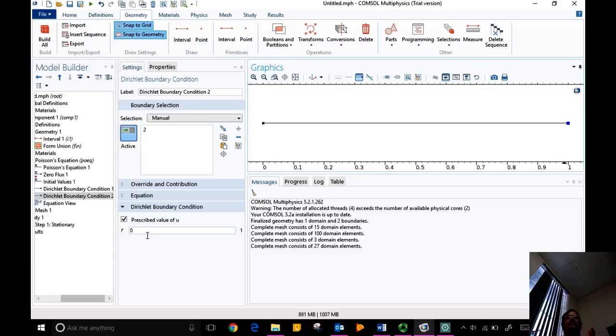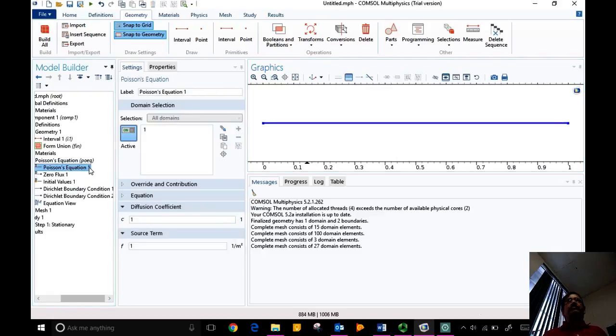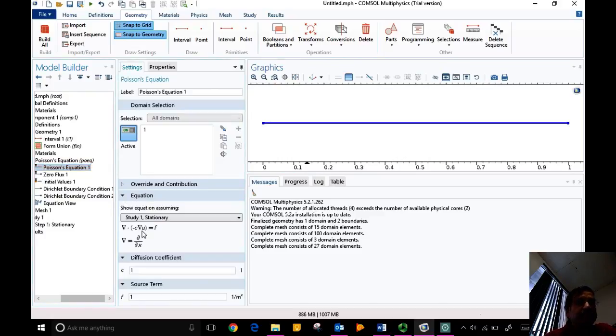So you have defined the boundary conditions, the geometry, and built the mesh. You need to specify what else? The equation. The equation has a form like this. Do you see here? Gradient, del dot minus c del u equals f. u is our unknown temperature, and f is our convective heat transfer term that we need to model. Okay? And if you want to model K as a function of temperature or A as a function of x, you plug all these through c. c is now set to 1. But you can put in a function there to model variable area, for example, if it is known.